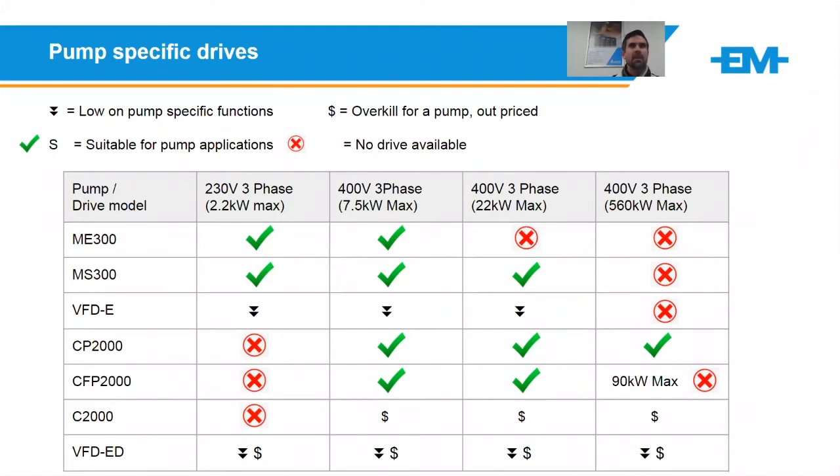Common in lift applications and hoists. I think if the building wants like a green stamp, they might need to do that. We've got one in our lift in Cape Town. And we also use a couple of them on our load test benches. So when we load up motors and test our drives, we use the regen unit to recirculate the regen power.